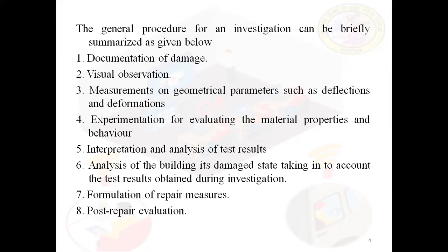That means after documentation, we have to do the proper visual observation, just by observing the damaged buildings. That also we have to note, or if required we have to take any photograph. After that we have to do the measurements of geometrical parameters such as deflection. For example, if it crosses its maximum deflection according to the codal provisions, we have to measure that.